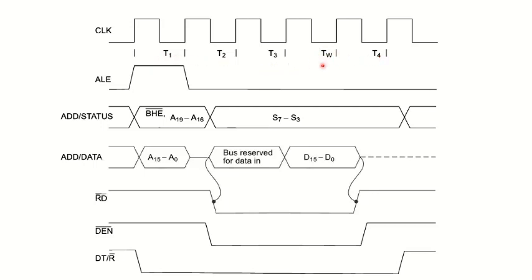Okay, this is TW, meaning waiting state, because microprocessor is a very fast device, and to access the data sometimes the microprocessor can wait for some time, because the peripheral devices or input output devices from which the microprocessor is about to read some data or information can also raise the ready signal with 0. So at that time microprocessor has to wait some time. So that is this wait cycle or wait clock.